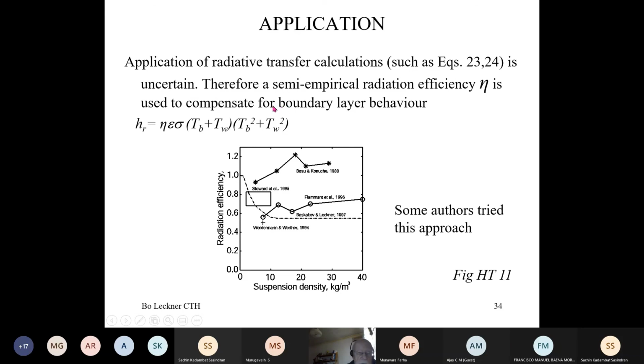Well, the heat transfer coefficient, as I have explained it earlier, is this one. And here there is an efficiency added. And the reason is that if we take the heat transfer coefficient of a circulating bed at the wall, you have a denser suspension than in the center.